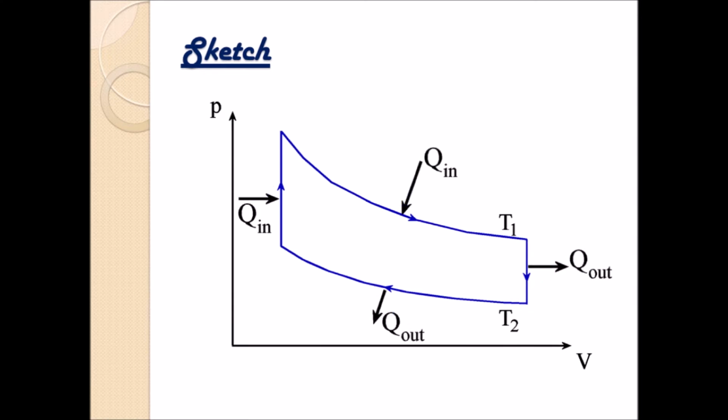Now, what does this mean with respect to heat input and output? When we're talking about an isothermal expansion, meaning the temperature stays constant, nevertheless, we will see that we need some heat input in order to increase the volume. Regarding the reduction in temperature from T1 to T2 in the second regime, we'll see that there is some heat output. And also, when we keep temperature constant then at T2 and reduce the volume again, we also have a heat output. Whereas keeping the volume constant finally in the fourth regime and increasing the temperature needs a heat input.